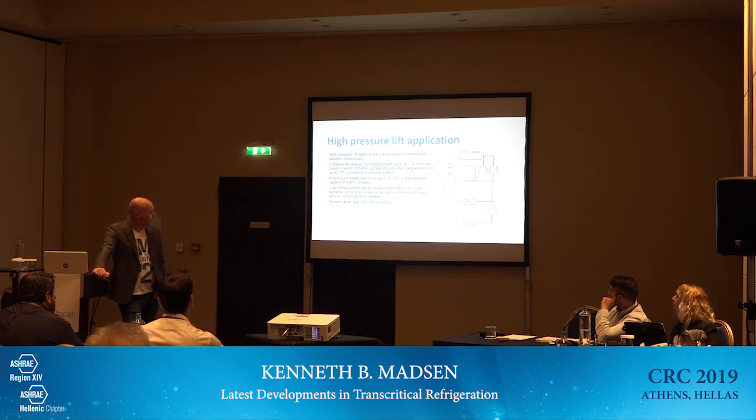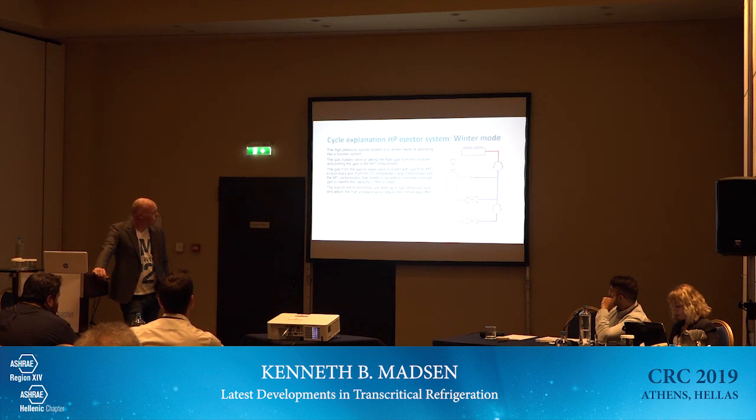And in summertime, the parallel compressor is basically substituting the gas bypass valve. So in winter time, the system is running like that. There's no flow to the ejector. There's no flow through the parallel compressor because the gas fraction coming down from the gas cooler is very low. So then we're basically back to the standard booster system.